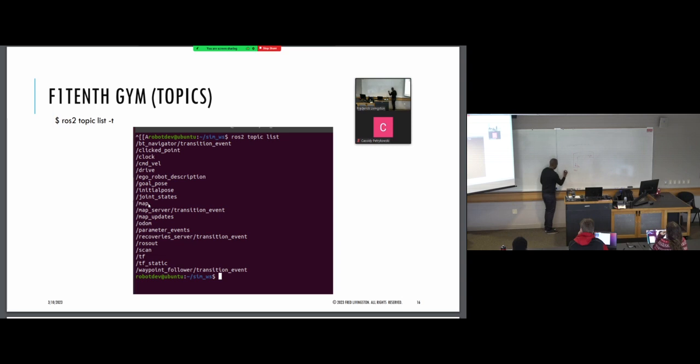That was kind of hard for me to draw. There, X, Y, Z is the coordinate system. Moving forward is always the X direction. If you initialize to a compass, that would be your true north, this would be your east, and this would be up. This is the convention for ground vehicles, and then north, east, down is the convention for aerial vehicles, for drones and such.